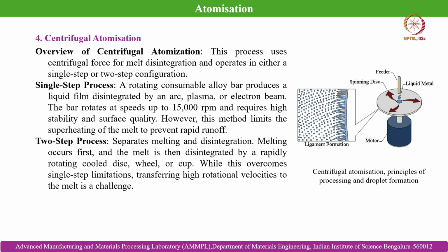Once we have discussed this fluidized media based disintegration of the melt droplets, now we move into centrifugal atomization. This process, like the capillary drop formation process, can be a single step process or a two step process. In this case it uses a centrifugal force for melt disintegration and operates in either a single step or two steps.